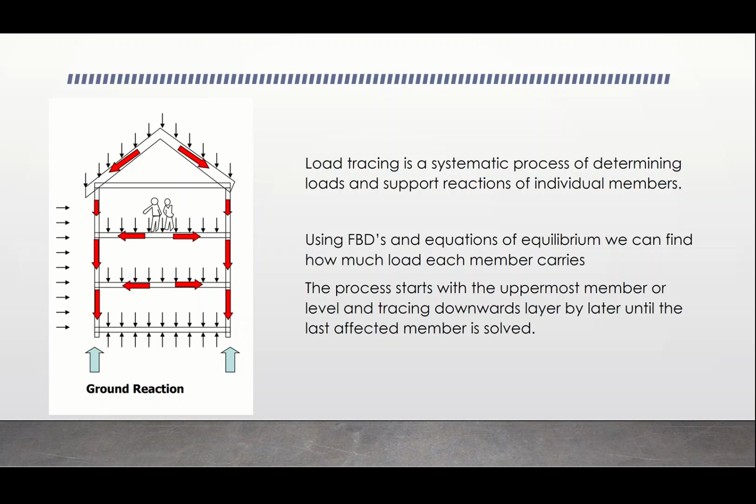So that is ultimately the goal of load tracing, is figuring out, okay, for this beam, how much is that? How much is the loading on that? Is it rated for that? Is it under capacity? Do we need to do something else here in order for it to be rerouted in order for that load to be lessened? So the process starts again with the uppermost, tracing all the way down layer by layer until we get a ground reaction.